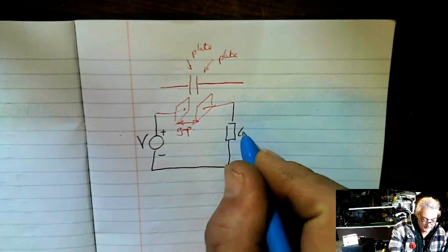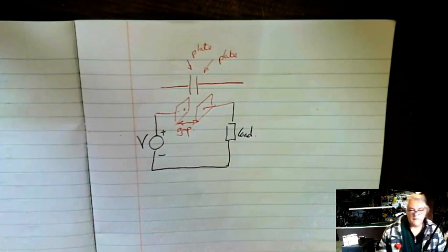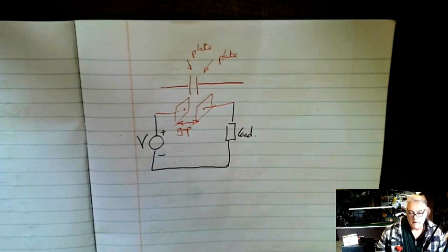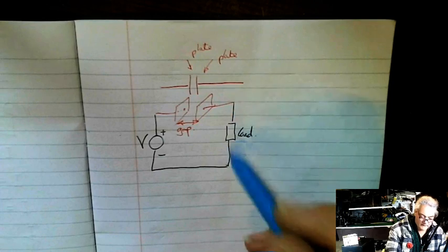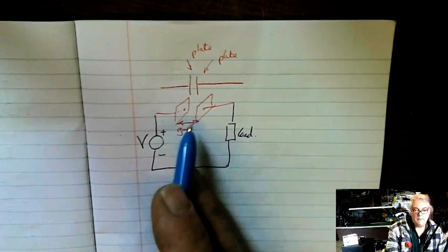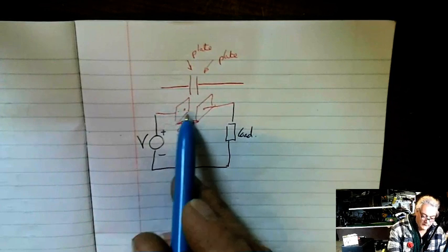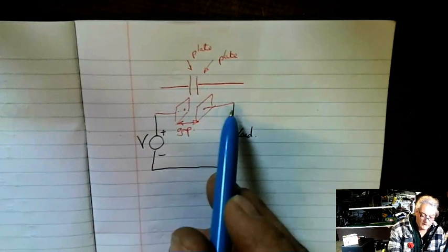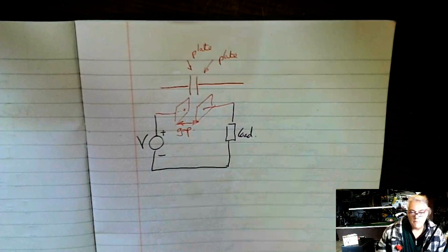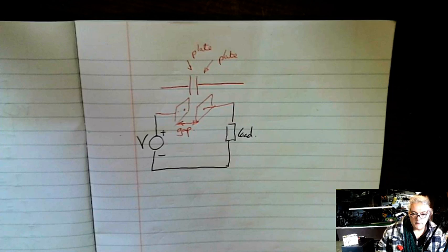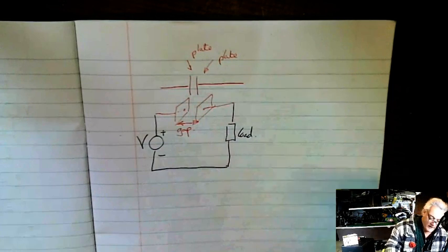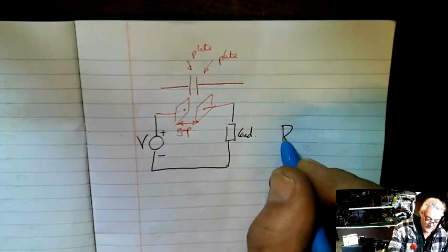We need a load for everything, and a load can just be a resistor. If we put a load on here and we connect a DC source to there, we're not going to expect much current to flow through the load, are we? Because this is open circuit. What we've done is taken a closed circuit, imagine this capacitor isn't here and there's just a straight wire going across here. It's a bit like we've just cut the wire, and it should come as no surprise that by cutting that wire and making that open circuit for DC, now think what DC is.